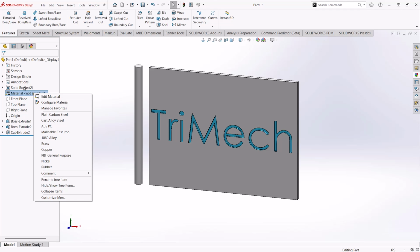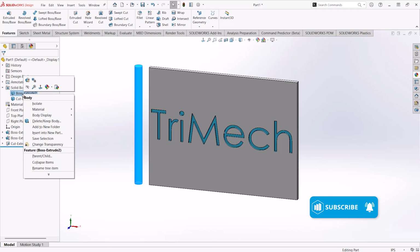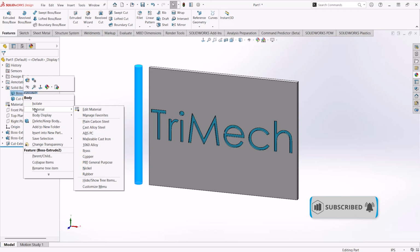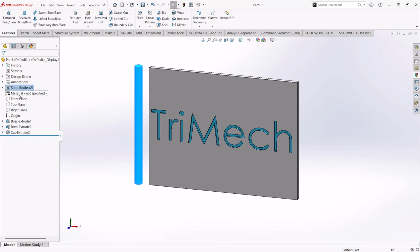You notice I have two bodies in my solid bodies folder. I can come in here and set my materials separately. So that way it's not just one material being applied globally as it is when we see it in the selection in the top of the feature tree. For today, let's just make everything the same material.